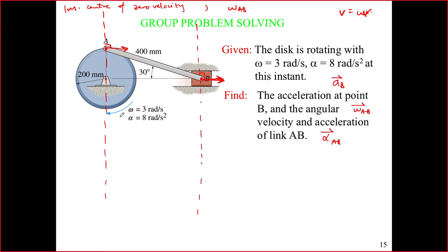basically if I was trying to find the instantaneous center of rotation, that would lie at infinity, as we had discussed before, right? Which case of motion was this? What is happening here? Both of them are moving like this, so translation. Exactly right, thank you. I think this is Munjar speaking. At this instant the velocities of A and B are parallel to each other, and it is as if this thing is instantaneously under translation. Instantaneously, by the way, remember, everything we are talking about is instantaneous.